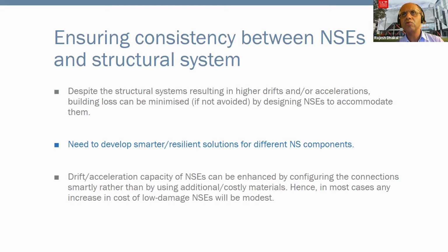It is just about thinking about their connection with the structural system, their clashes with other non-structural components, providing the required clearance, and coming up with flexible connections so that they behave uncoupled from the structural system. So it is not necessary that a more resilient non-structural component is more costly. Any increase in the cost of low damage non-structural elements will be modest.